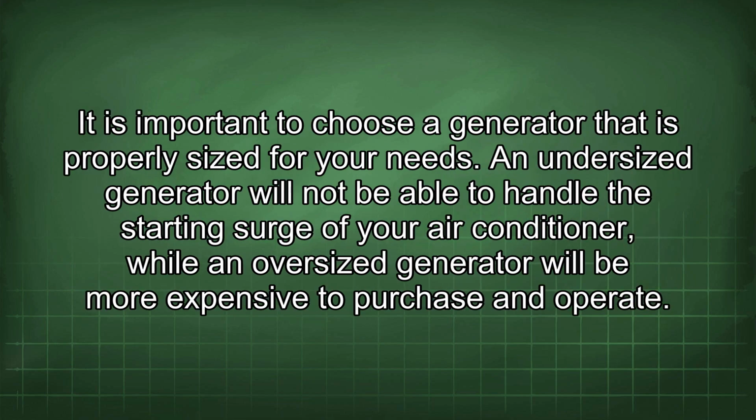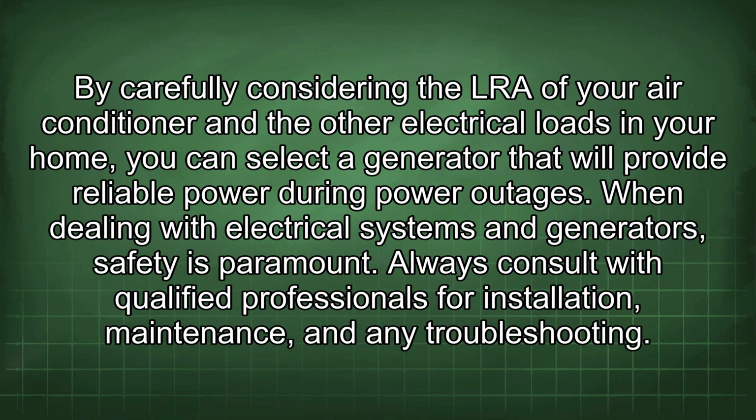It is important to choose a generator that is properly sized for your needs. An undersized generator will not be able to handle the starting surge of your air conditioner, while an oversized generator will be more expensive to purchase and operate. By carefully considering the LRA of your air conditioner and the other electrical loads in your home, you can select a generator that will provide reliable power during power outages.